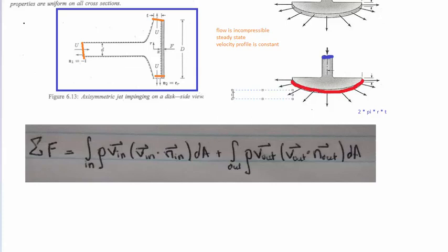The reason we need to do this is when we're writing our linear momentum equation with this cross-sectional geometry, you need some sort of way to say that the symmetry cancels out the forces. So in other words, when you write a force equation for the radial direction and everything's spraying out radially, you know that this vector over here of the fluid coming out at this point is going to be completely equal to whatever is pointing out over here.